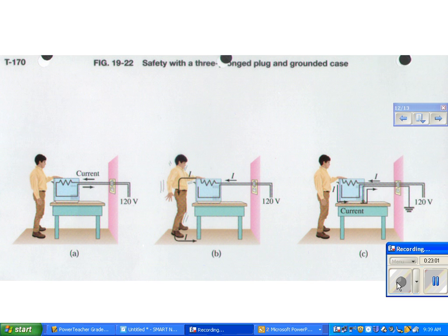I think this is like what you talked about, Todd, you're asking about. So think about your home for a second. In the bathroom, the outlets in your bathroom are usually different than the outlets everywhere else in your house. How are they different? What do you notice? They have the little reset button, okay? And the kitchen will have it too. Sometimes the kitchen will have it too. Excellent. Notice in your bathroom and in the kitchen, you're near water.